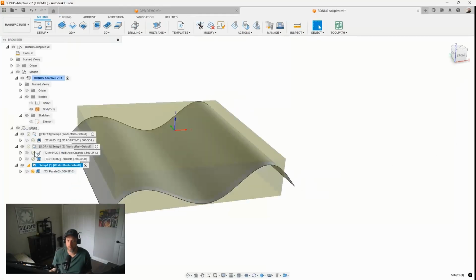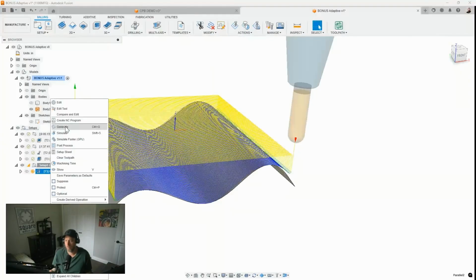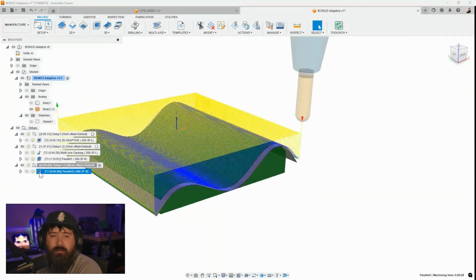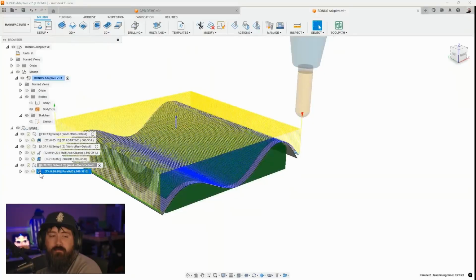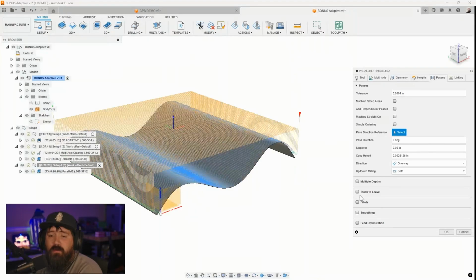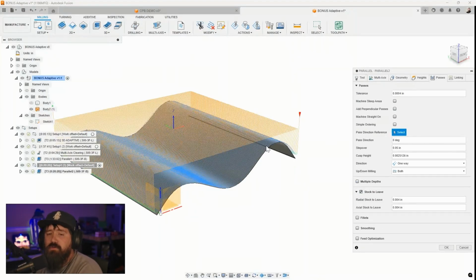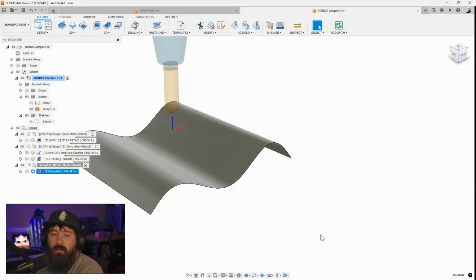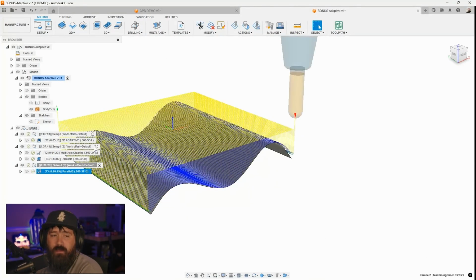Can you also use a bullnose tool for that? Yeah, you can use whatever. I mean, not whatever, but you could use a bullnose. You could use a flat tool on this also, but you'd want to leave some stock there. So I would usually do this for a roughing or semi-roughing over a part, especially with a big chamfer or something like that.